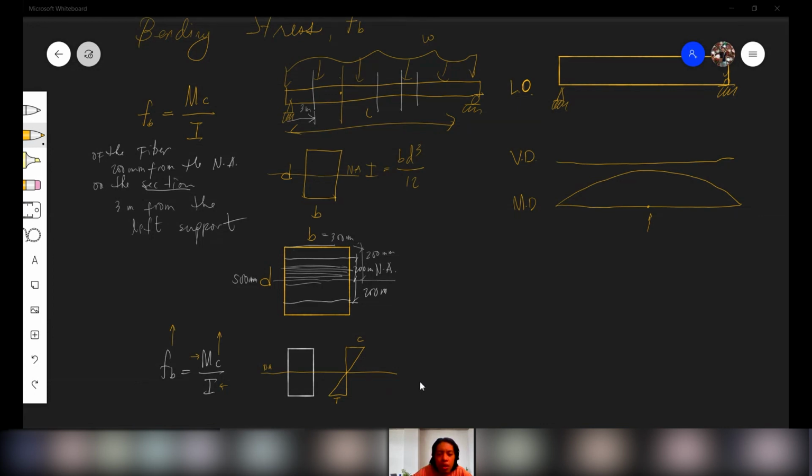Anyone? Anyone, how can you solve for the maximum moment? Moment diagram. Miss Hermoso. Mr. Elio, thank you. How can you solve for the maximum moment? One, first solve for the reactions if there are any. Then cut sections and draw the diagram.